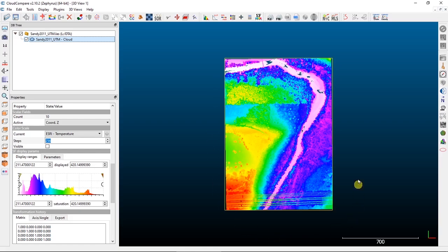Before you get started on any kind of point cloud extraction, it's usually a good idea to make a clone of your point cloud within CloudCompare. The good thing about a lot of the editing and extraction that we can do in CloudCompare is that it's not destructive to the original file, unless you save over it, which takes some effort. The base operations that you can do in CloudCompare are non-destructive.